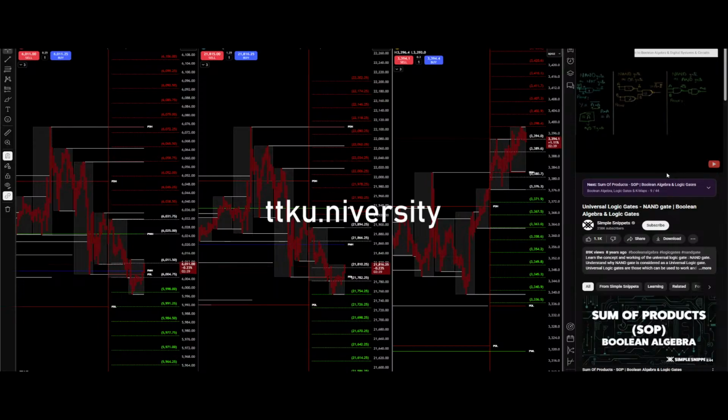For the first NAND gate, we supply A as the input. For the second, we supply B as the input, and we get the respective outputs as A complement and B complement. Now we know how we got these values, since we just saw that it is operating as a NOT gate in this case. But for the third NAND gate, we supply these values as input.